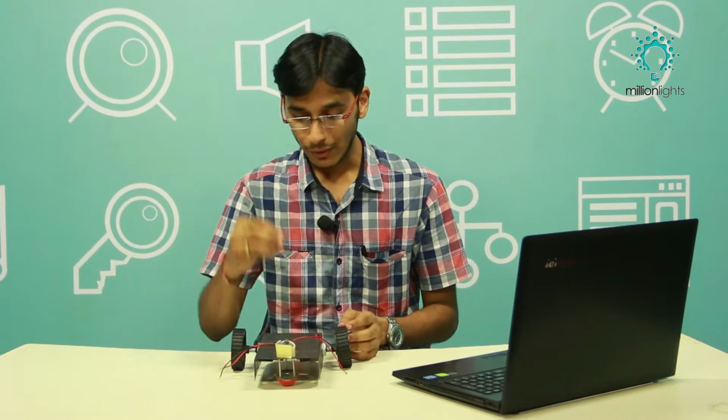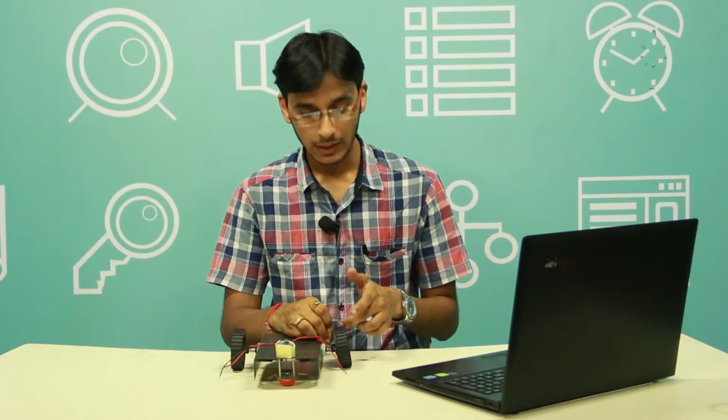Now one additional thing I would like to give you is that, if you want to turn 90 degrees, how to do that? There is no such instruction as turn 90 degrees. So you have to calibrate the time required by it to rotate, or what you can do is you can identify the RPM of the motor, and then along with that you can identify the diameter. So based on diameter and RPM, you can find out the time for which I have to give this instruction to move forward. So these are few techniques and tricks that we are going to use.